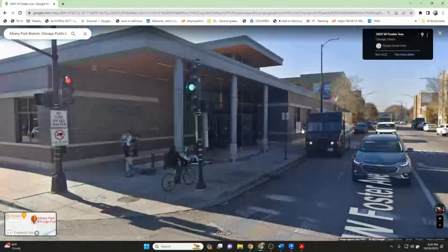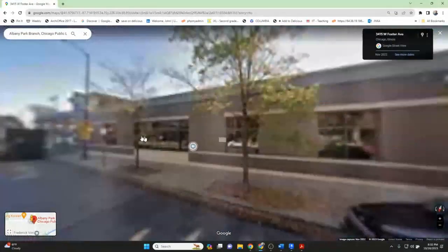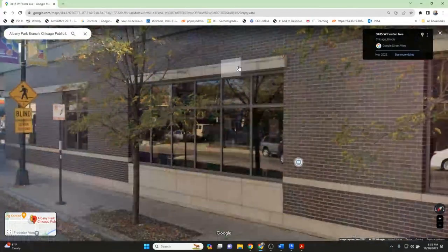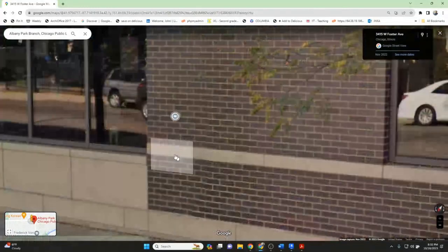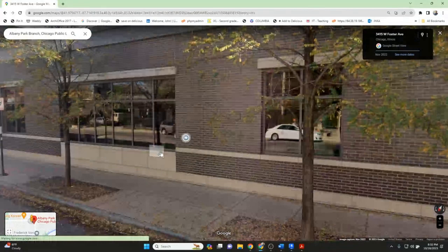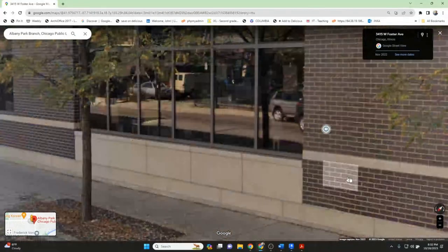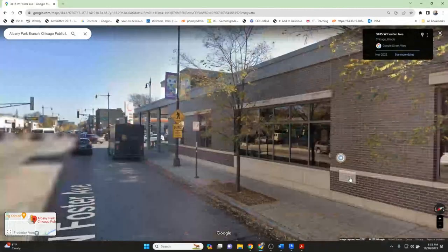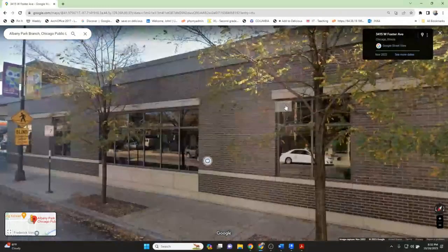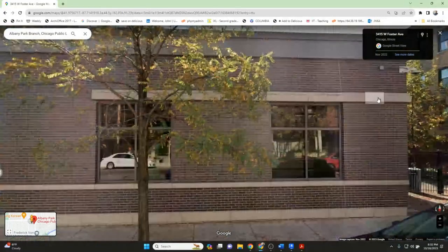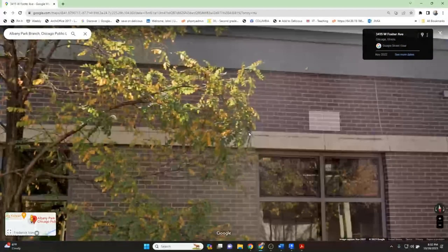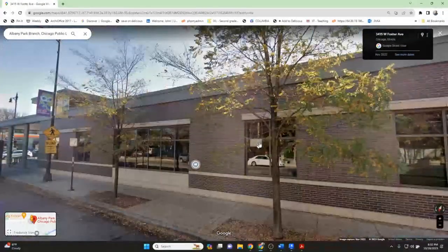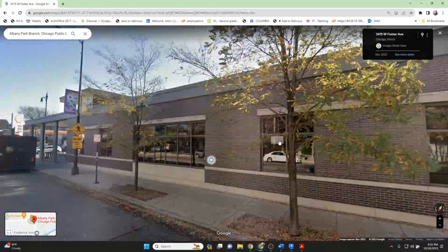So for example here, this is a profile sticking out the top of the windows that needs to be added to the model. There's a horizontal profile here added to the model. There's a piece here that's a different material than the brick that needs to get added to the model. And so these details need to be incorporated into the project. We've done this one just now, this one here, but now we're going to pick up a few more details. So we already have some of the skills we need because these are all custom profiles.